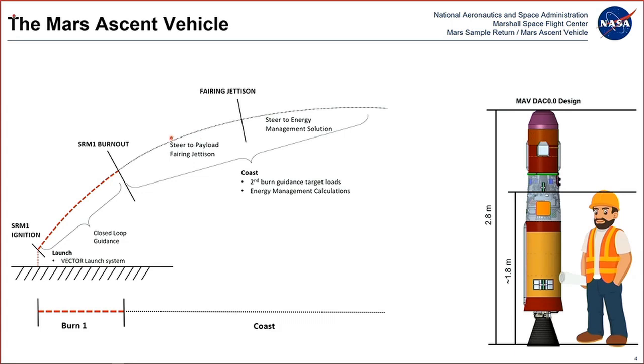First objective is to steer to a safe attitude that we can jettison our payload fairing. And then after that, we start computing this algorithm that I'll be talking a lot about today, called energy management. Essentially, the energy management algorithm is responsible for finding one specific pointing orientation that the spin stabilized upper stage can achieve under, again, very tight constraints, right?